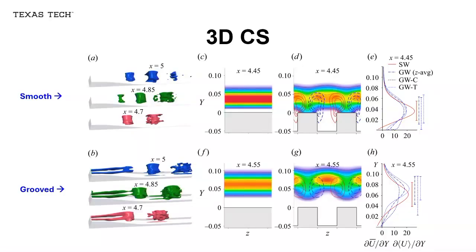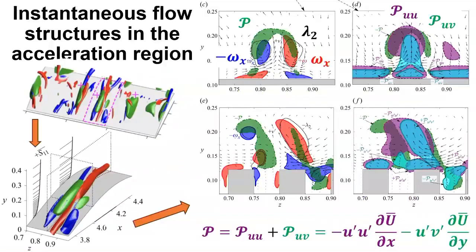So the shear layer where these spanwise rollers are being rolled up is a much more diffuse shear layer compared to the smooth wall. And this is part of the explanation why the turbulence production is actually lower. It's because of that interaction of the streamwise vortices inducing a corrugated, more diffused shear layer, while at the same time helping organize the spanwise roller to remain for a longer time in that shear layer without breaking up. Okay.